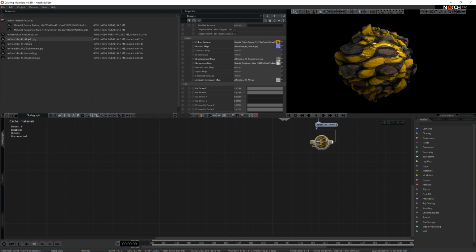So how do you convert the existing texture that is in JPEG or PNG or any other format, and how do you make it into a DDS file? Well, you can do that just by right-clicking on the texture that you want to treat, and then you will be brought into the options property. And here you have three choices. Either it should be RGB, RGBA, or grayscale. Now I see that all of these textures are RGBA, so I would choose the property compressed to DXT5 RGBA.